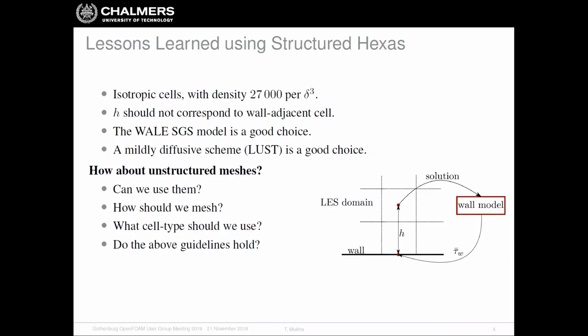We had very good experience with implicit LES with standard well-resolved LES simulation in OpenFOAM. So that's become our go-to approach: turn off SGS modeling altogether. But with wall-modelled LES it doesn't work, so you should use an SGS model, and the WALE is a good starting point.